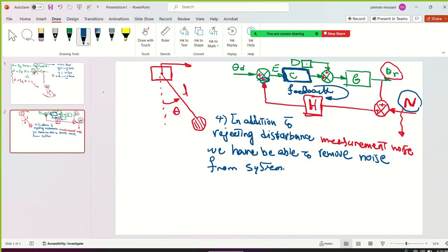So if this is the disturbance, as we know, whatever sensor you have that measures this angle, maybe you have some dust in the air, maybe this is just the laser measurement system, the dust affects the measurement. So you have to design a controller that keeps, for example, the angle of this at 45 degrees. This is desirable, okay?